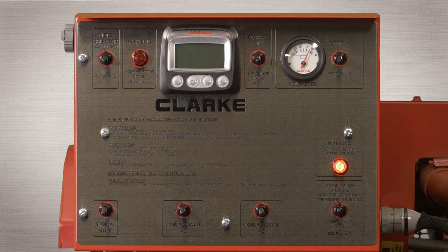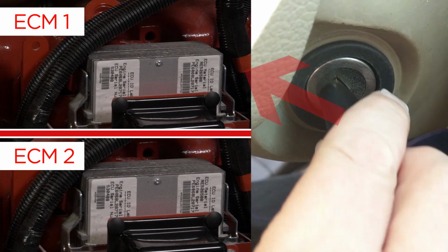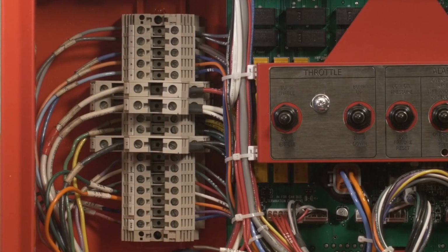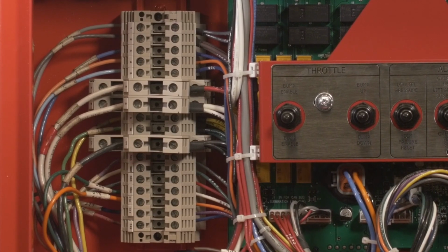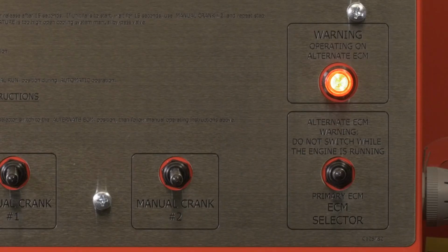The process of changing ECMs with the hand selector switch happens instantaneously, much like turning a key to a car's run position. As soon as the switch is activated, all engine sensors are switched via relays inside the engine panel. The engine can be started at any time after the ECM is switched. No waiting is necessary. The ECM should not be switched while the engine is running, as instructed on the faceplate of the engine panel.